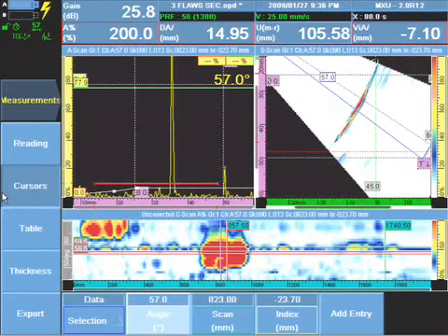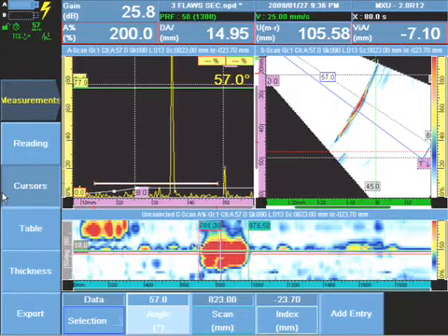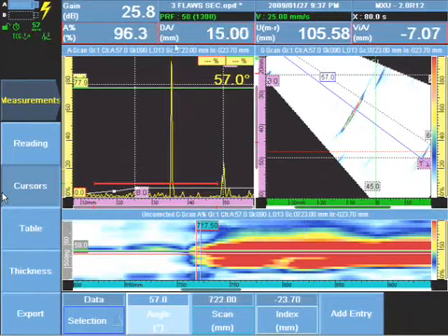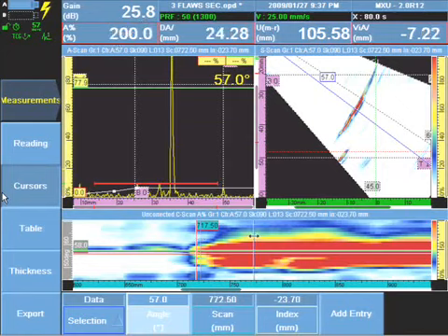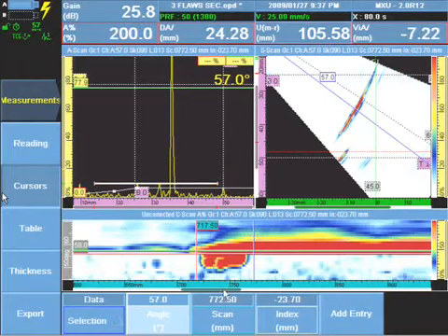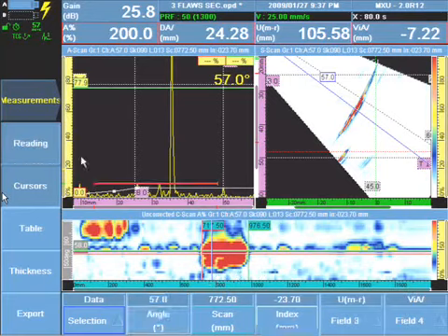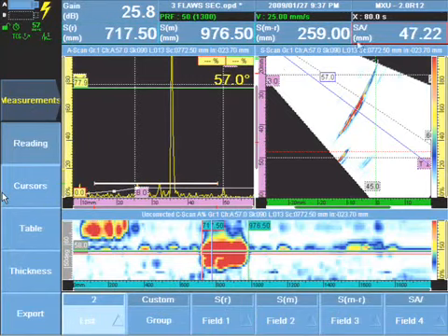The length of the flaw is recorded on the C-scan either by doing a 3 or 6 dB drop on the color palette, or using the data cursor and the amplitude reading to take a digital number for our 6, 3 dB drop, or whatever the code and the procedure requires. The delta between these two cursors on the scan axis is the length of our flaw.